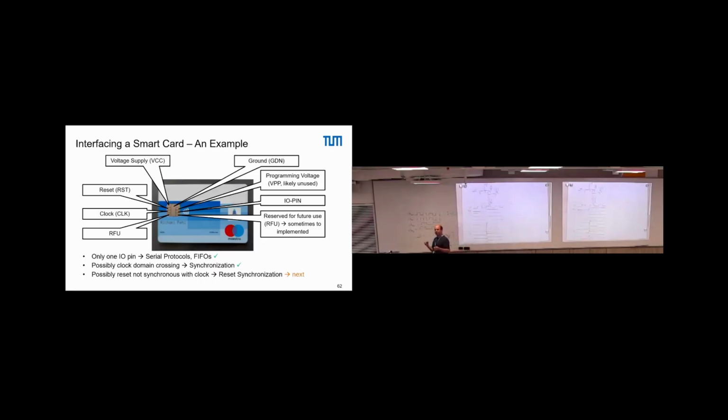You can also implement a reset that is active 1, and maybe that's a good chance to tell you that this is a frequent mistake in many designs: one half of the group tries to implement a reset at 0, the other half tries to implement a reset of 1. Both test independently, both systems work perfectly fine, you plug them together, and at the end nothing works, because always one of the parts is in reset. So it's a critical point indeed.